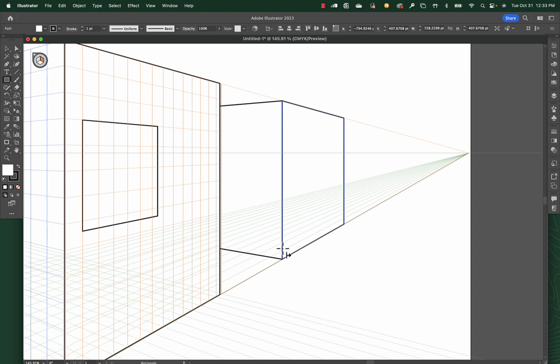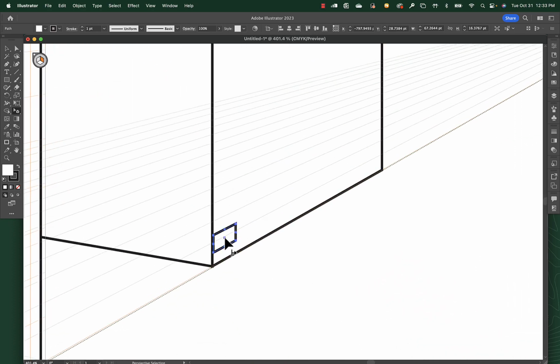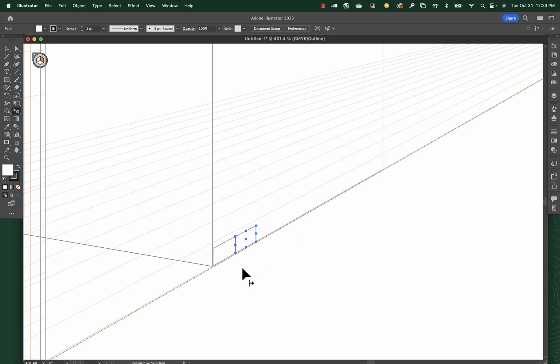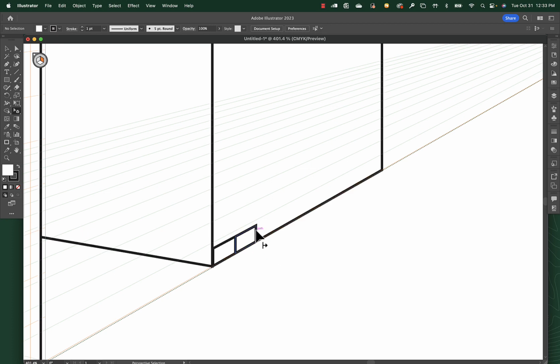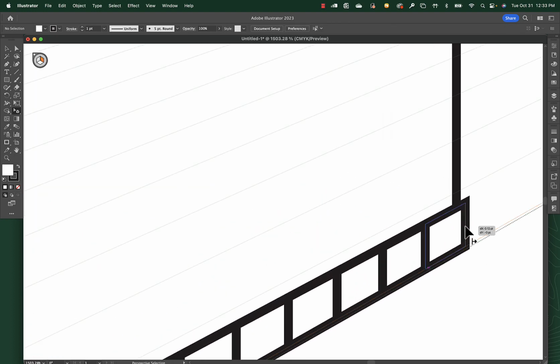What if I wanted to make this a brick building? So I'm making sure I'm in my right grid. Going to just draw a little shape here. I'm going to zoom in a little bit more. Start my grid down here. Option drag it to snap it. Command Y. You guys all know how I'm a fan of artwork mode to make sure that things are aligning where I want. There's no glaring gaps. So I option dragged this to make a copy of it. We all know that Command D will repeat that transform and it keeps it going. So now I can just shorten up this one.